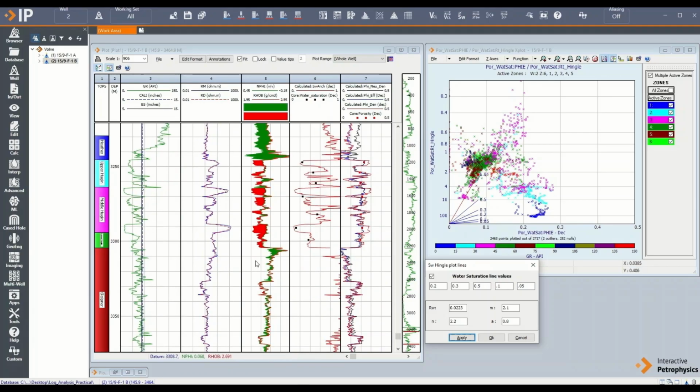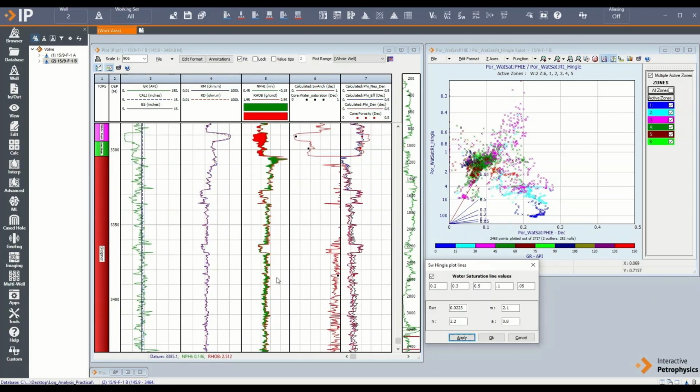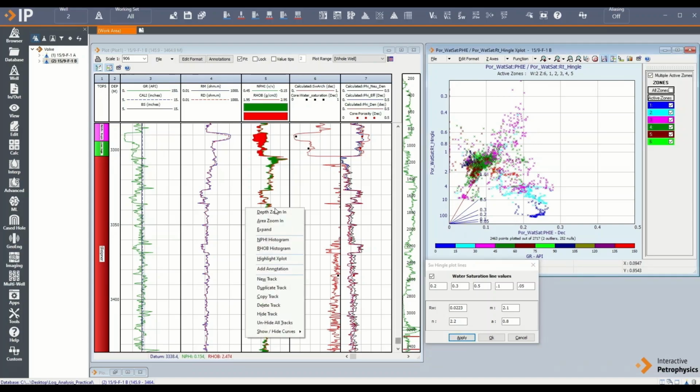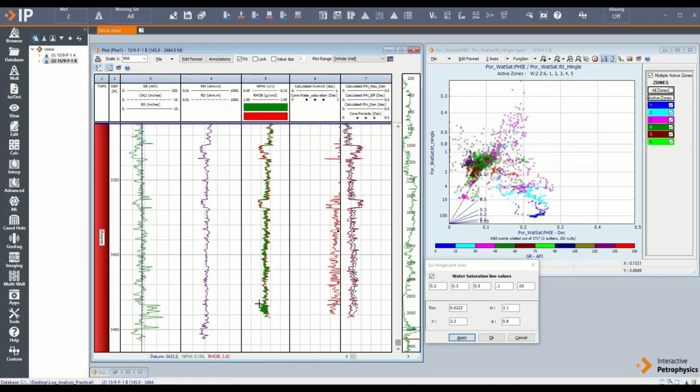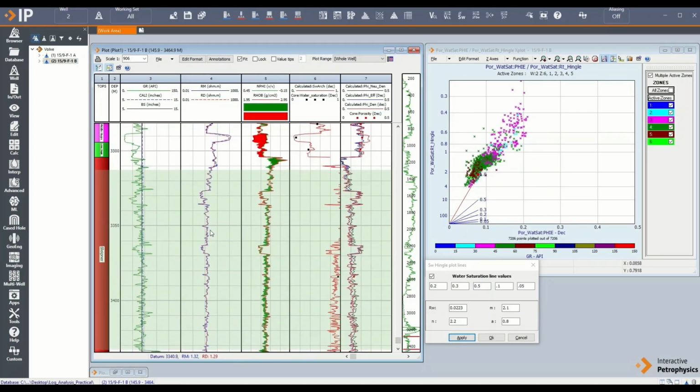Last time we used the Sleipner formation in the Pickett plot. You can see the clean sands, relatively clean ones, in the Sleipner plot somewhere in this zone. And if we want to choose just the points in Sleipner for our fitting purpose, then we can right click here and highlight cross plot, and then we can highlight this entire zone. You see, by highlighting that entire zone, we only have those points displayed which are highlighted here.